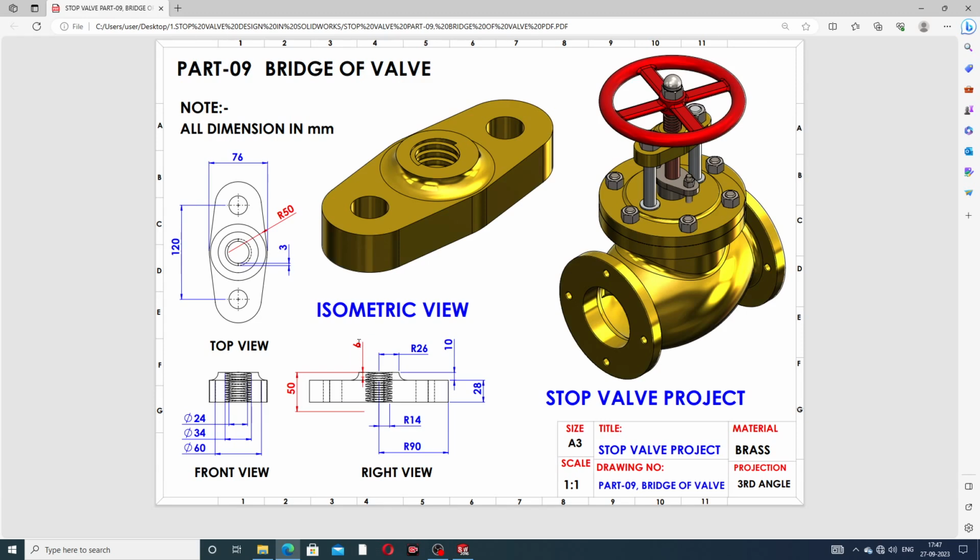This is the pitch, and this is the height and pitch, and height and revolution. This revolution is 6, this turn is 6, and this is a 50 millimeter height. This thread is used here. On both sides of this 50 millimeter a fillet is used here.